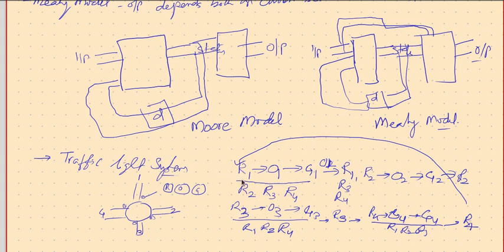But still it is not very realistic, because whatever we are doing is blind. We are not following how much traffic is there on each lane. If we can know the traffic in each lane, then the green can be controlled according to the traffic. If traffic is more in lane 1, make sure that green is on in lane 1 for a very long time compared to the other three greens. In the same way, if lane 3 has more traffic, then lane 3 green should be on for a longer period.